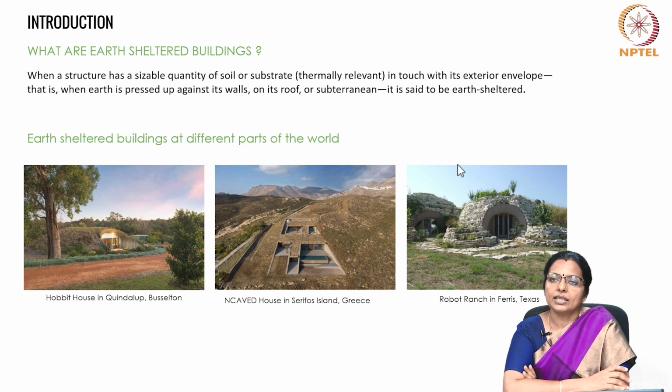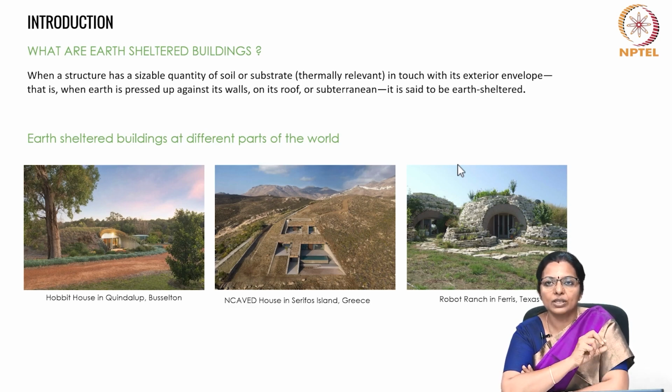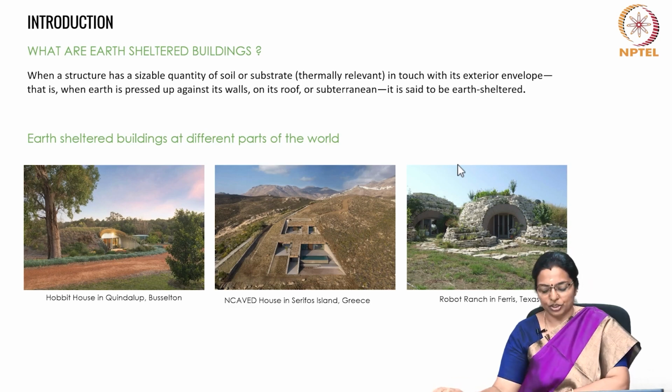Earth coupling is where concrete floor and sometimes even walls are in direct contact with the earth. In a well-insulated, properly shaded house, this draws up the stable deeper ground temperature to the surface of the floor, which gives the house a head start in regulating its temperature.